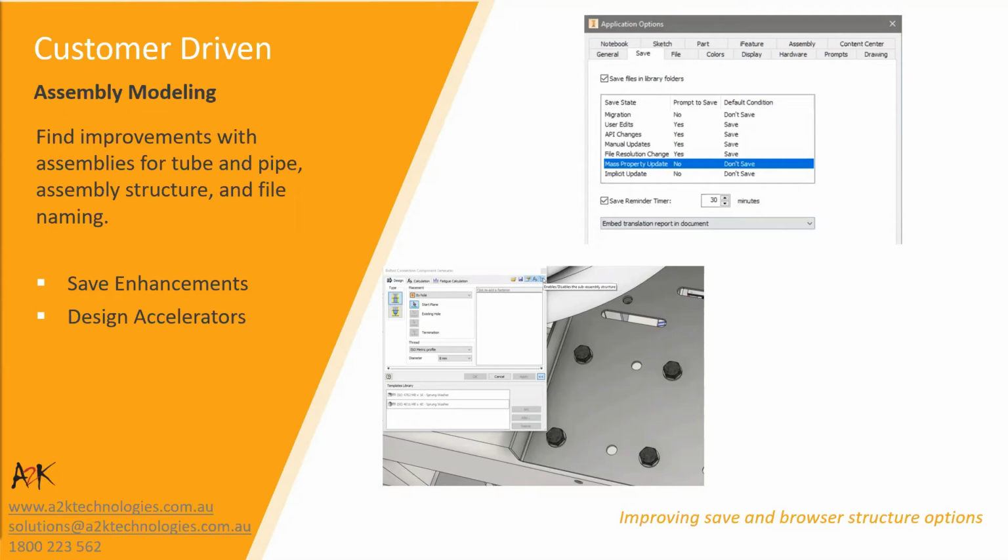You can use the new save files in library folders checkbox to control the default condition for saving files in the Content Center library. But when deselected, files in the library paths do not display in the save dialog box and they are not saved. So just be aware of that.